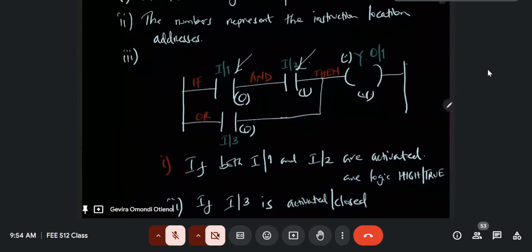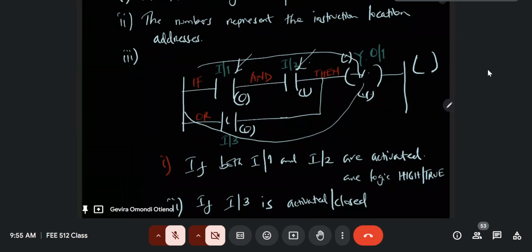But that output, we just write the state of the output, okay? But we don't update it. It doesn't affect what happens here until we also go and check the one for this, because, remember, we are running from left to right, top to bottom. So we'll go like that, then write the state. But we'll also have to come back and go through this and then write the state.